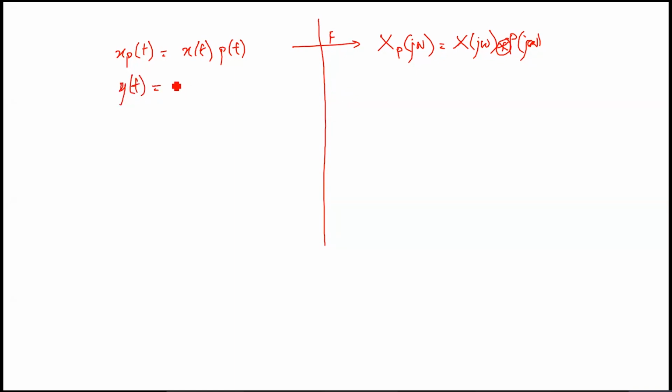you still may remember this: convolution in the time domain ends up becoming multiplication in the Fourier domain. This we know from our previous knowledge of properties of convolution or properties of the Fourier transform. So this was H(jω) times X(jω). So convolution gets converted into multiplication. Now if you have multiplication, that converts into what is known as circular convolution.